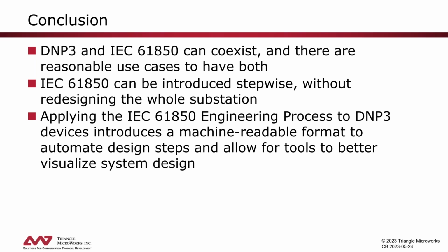And then finally, I hope that we've demonstrated that applying the 61850 engineering process to DNP devices introduces a machine-readable format in the form of the SCD file and then the different proprietary CSVs or DNP XML device profiles that you generate from that. And that automating these steps allows for tools to better visualize your design.